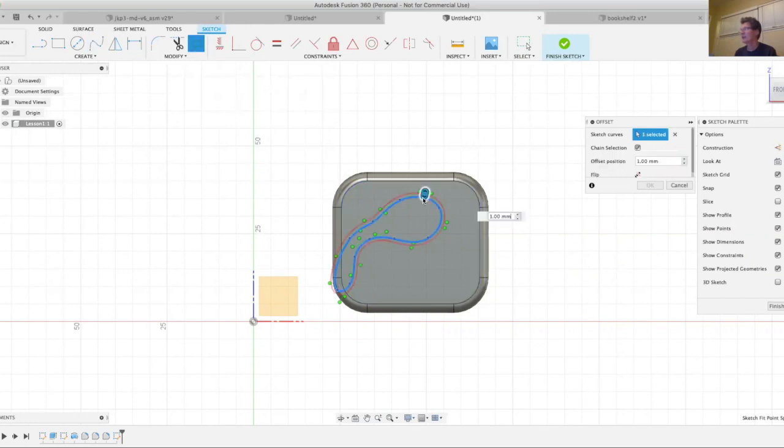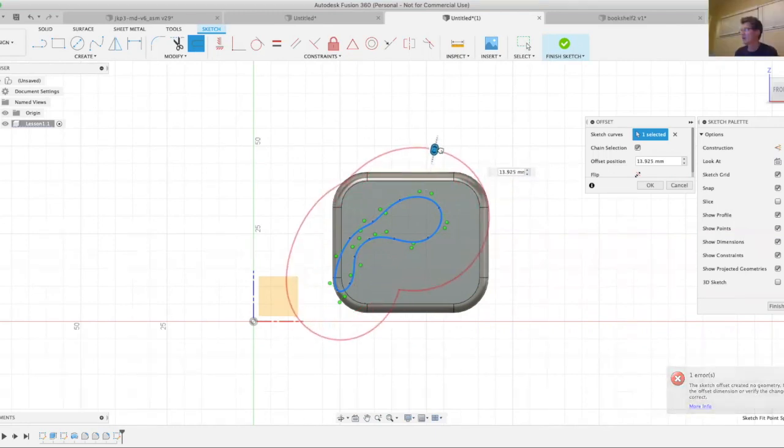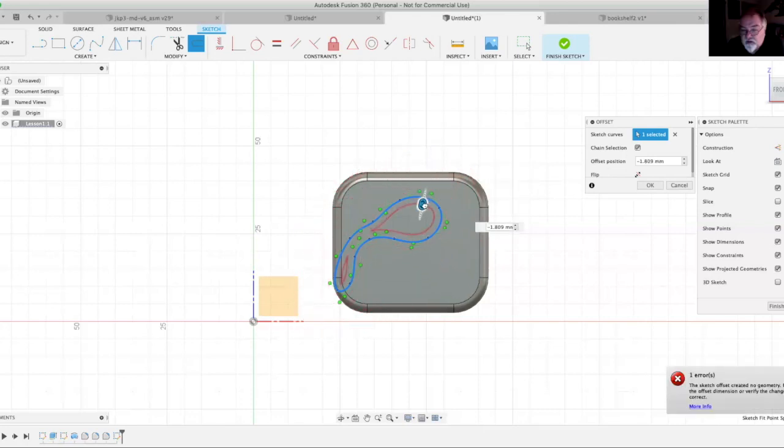It's mathematically not an easy thing to do, and I've seen various glitches in Fusion 360. You see this radius getting very small here, right? As we go further, it actually handled that one not too bad. It gave me an error message. I use the canvas feature a lot, and everything I read recommends using the 3-point arc and not the spline, for exactly what you're saying.